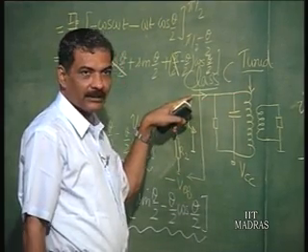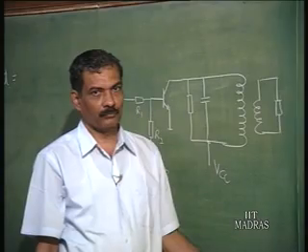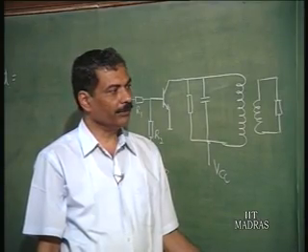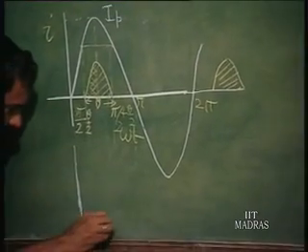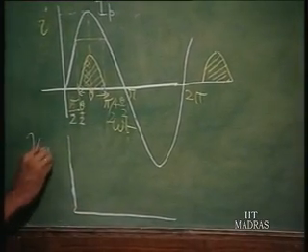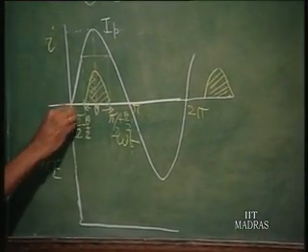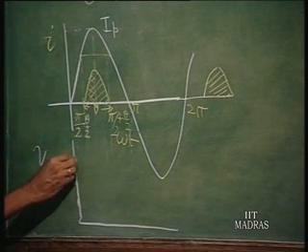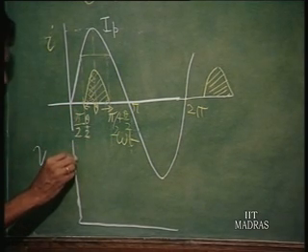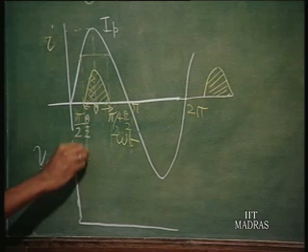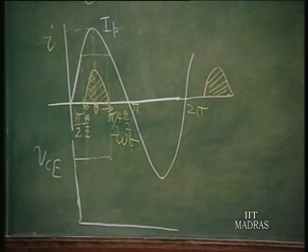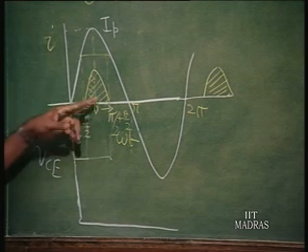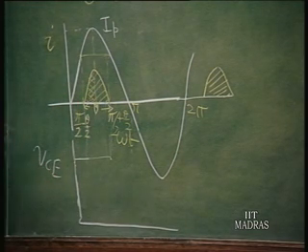So, the potential here is going to be VCC, no current is there. So, if you now plot the voltage VCE as a function of time, it will start at this point with VCC, because there is no current all the way up to this point. Thereafter, this current pulse is going to generate only voltage waveform corresponding to fundamental.